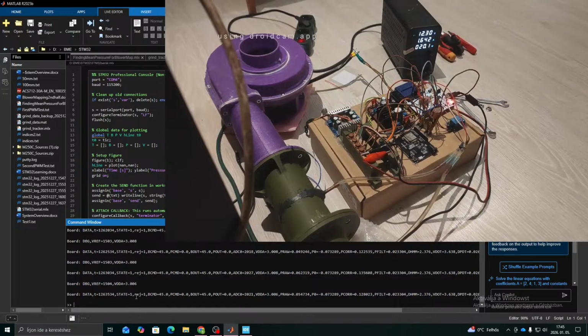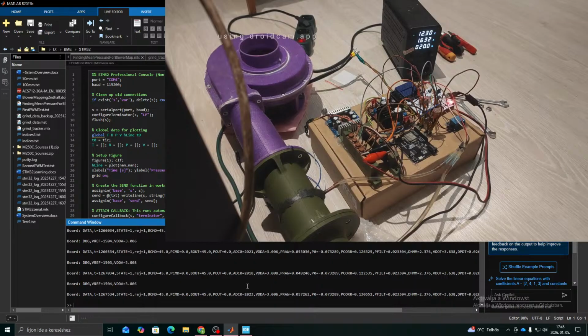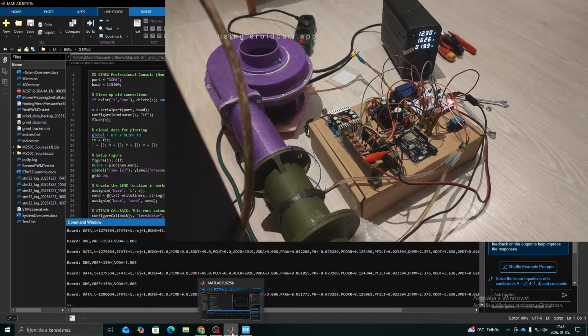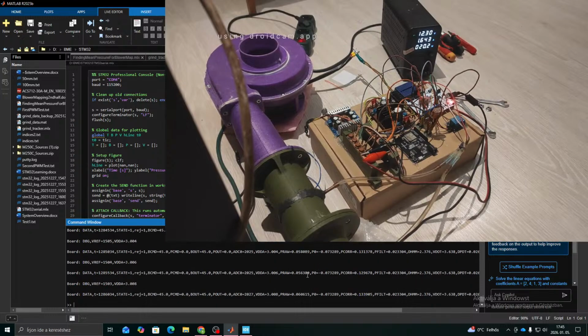But when I was running it at 80%, it was shooting all over the place. It was deviating around 100 ADC, which is kind of a lot. When you have big deviations, you have this filter in the code that rejects these very intense big jumps, basically to not gather bad data.